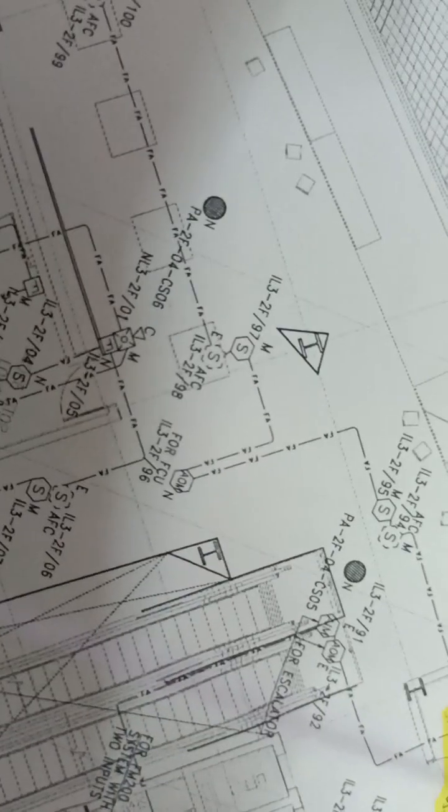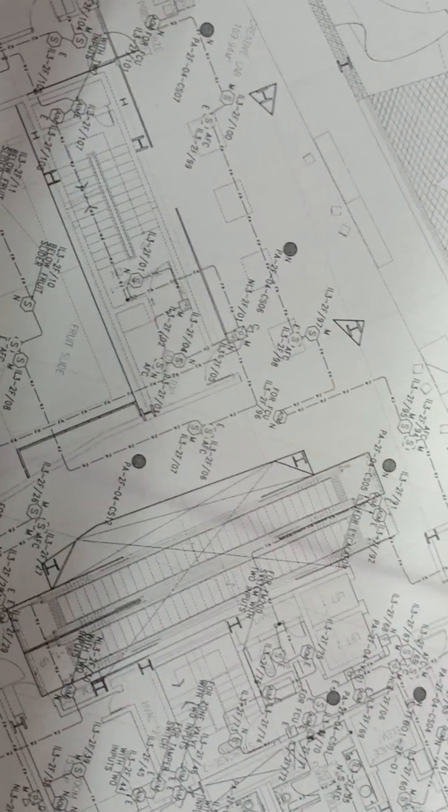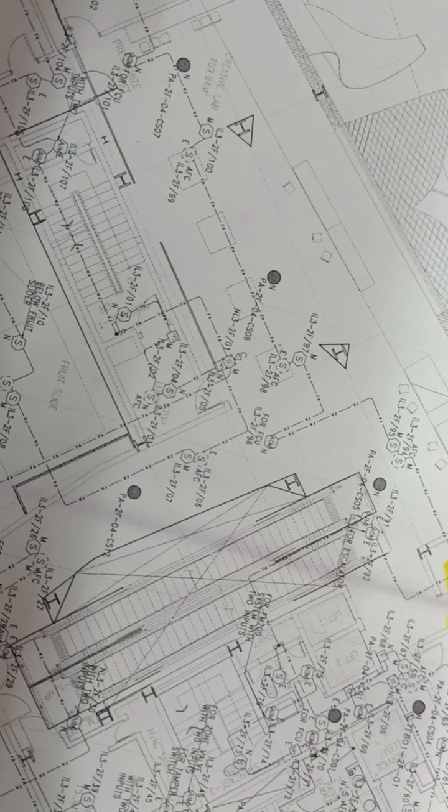So it's very simple. The wiring is also very simple. Before, the sounder and smoke detector were in one loop, but now as per QCD requirement, a separate circuit shall be pulled. A separate circuit shall be done for the smoke detector, and a separate circuit shall be done for the sounder. I will show you some sounders here.